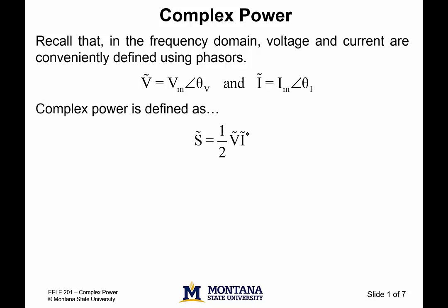Here is the equation which may be used to calculate the complex power associated with an element. In the equation, S phasor is the complex power associated with a given element. While the equation is essentially a voltage times a current, the typical unit used to denote the complex power is not watts. Rather, it is the volt amp. This is done to help reinforce that one is talking about complex power, which in general will have two parts, a real part and an imaginary part.